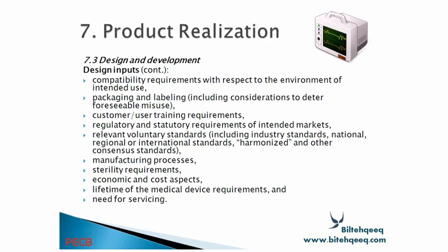Design input continuing: compatibility requirements with respect to the environment of intended use, packing and labeling, including consideration of measures to deter forcible misuse, customer user training requirements, regulatory and statutory requirements of intended markets, relevant voluntary standards including industry standards, national, regional or international standards, harmonized and other consensus standards, manufacturing process, sterility requirements, economic and cost aspects, lifetime of the medical device requirements and need for servicing.